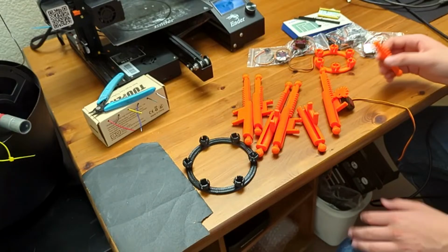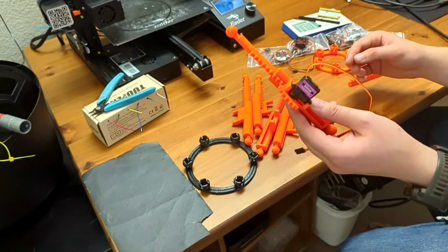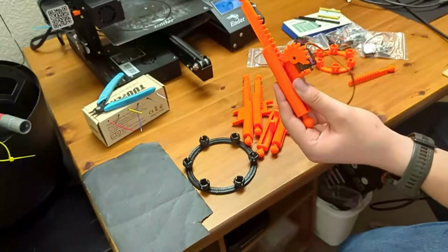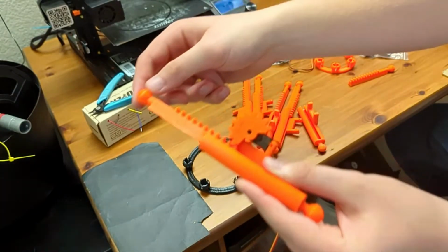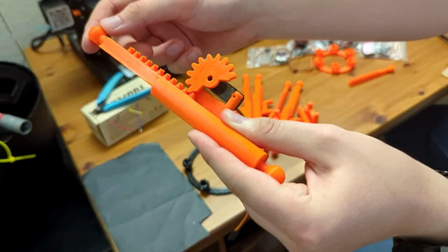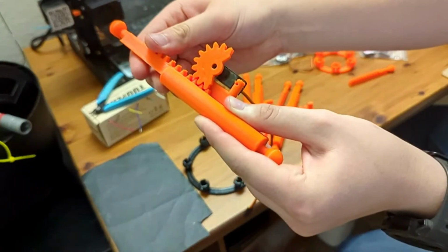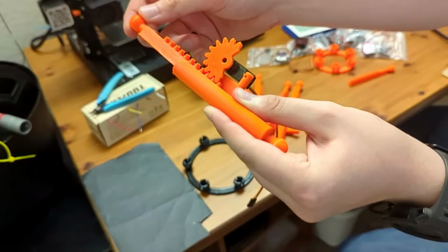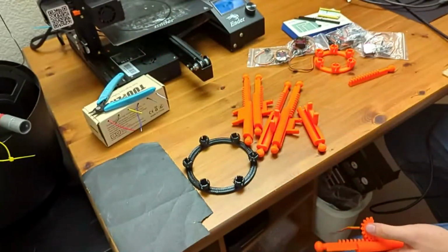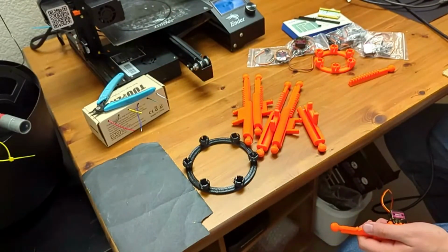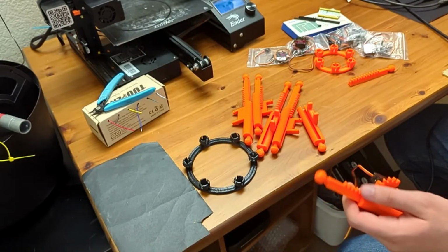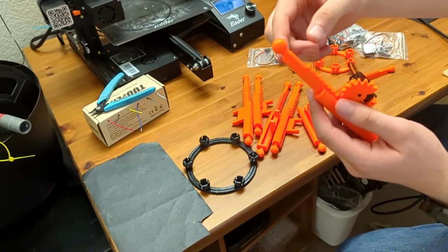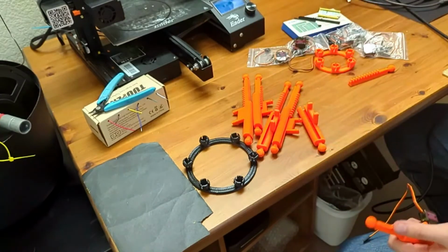But then there's also going to be some slop. In this one assembled one I have, there is slop. You can see how much movement there is, which is only going to amplify, I think, with having all six of them. So maybe that's a case where using an eight actuator design, like I was talking about earlier, could be really beneficial, because that could cancel out some of the slop since there's so much over-constrained motion.